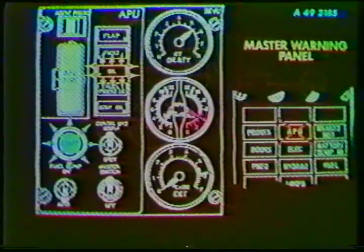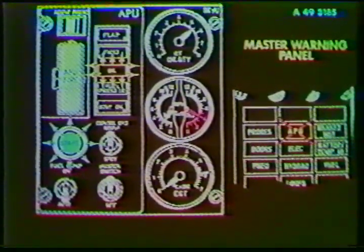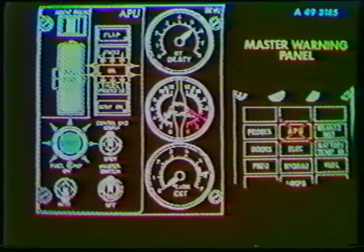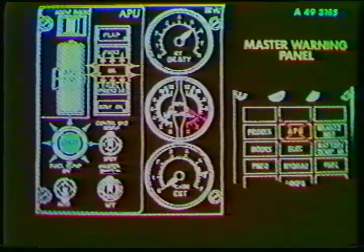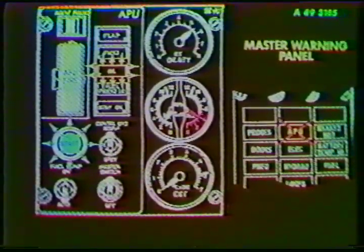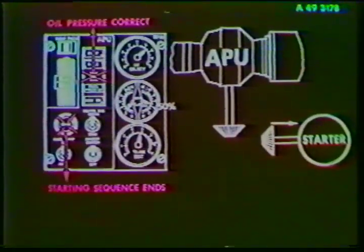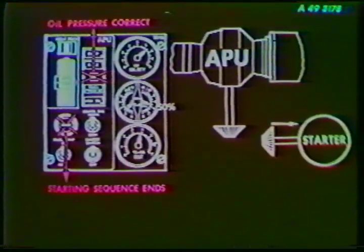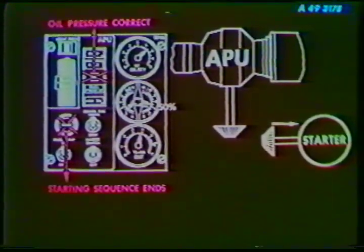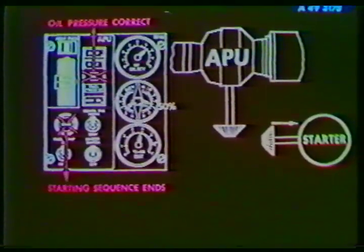During the starting sequence, the amber oil light will illuminate, the same as the start push button. They stay on until N2 reaches 50%. On the master warning panel, the APU warning light will be inhibited. When N2 reaches 50%, the APU is self-sustaining and the starting sequence ends. The start push button light extinguishes, also the oil warning light if the oil pressure is correct.